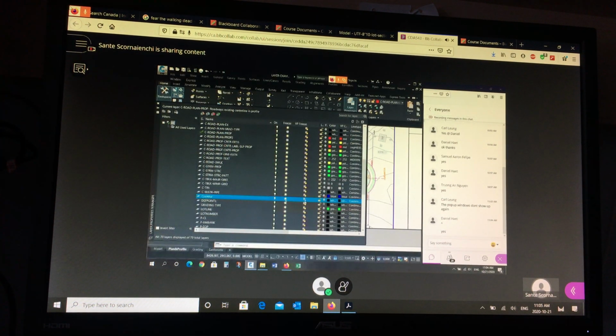All right, so then if you find the layer called corridor, you'll see that I didn't use this freeze. If I freeze this, it's frozen everywhere. So I want that on so I can still see it in model space. I want to freeze in this column, viewport freeze. So the current viewport that I'm in paper space, but I clicked into the model space through the window. And when I use this icon here, it freezes it in the viewport, not in the entire drawing. And that's really the secret here.